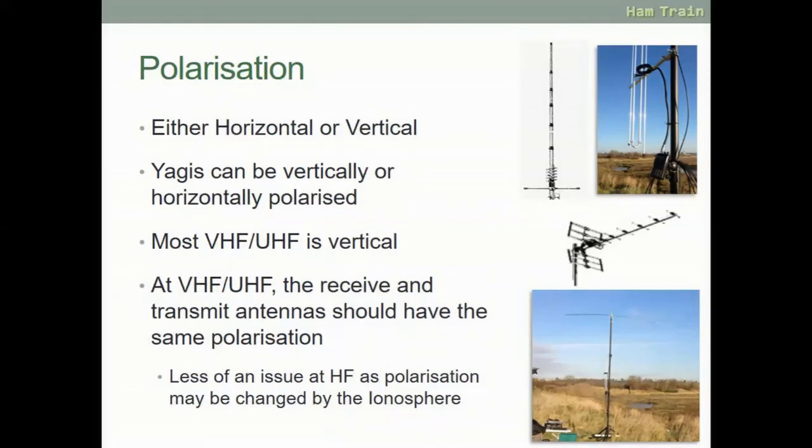If you are on VHF, UHF and your polarization isn't the same, that doesn't necessarily mean that a contact cannot be had. I very often transmit on a vertical antenna on single sideband, talking to people who are on single sideband on horizontal antennas, and we still make contact.